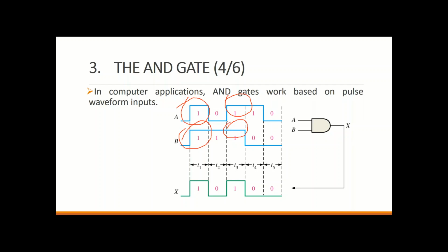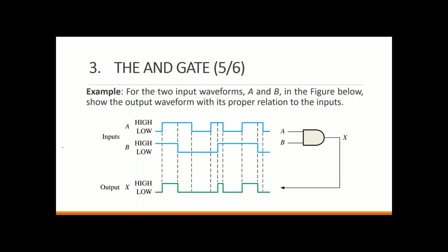Okay, sketch. Take the timing diagram from the edges. This one is high. Then the rest is 0. Why? This has 0, this has 0, this one has 0, and that's it. Why do you take a shortcut in this case? For just making your job easier and quicker. Because if not all of them are high, then take a shortcut, or a short circuit. It is immediately 0 or low.